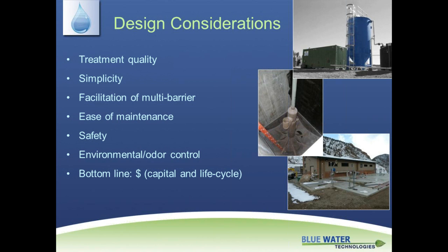A lot of people can get around that by having additional impoundment or holding capacity on site, where if they have to do some system maintenance, they can store the water and then treat at a higher rate as they come back online. So what the site requirement is in regard to treating water during maintenance activities or during washouts, whatever the case may be, is definitely a consideration throughout the process.